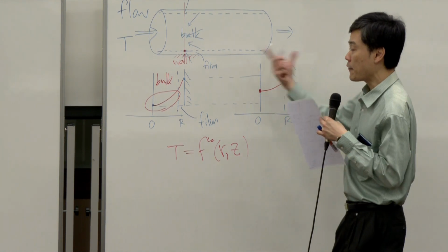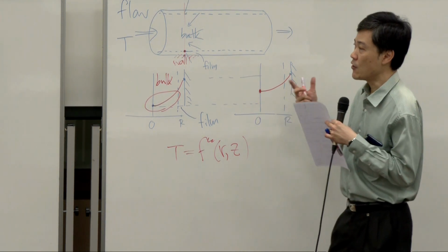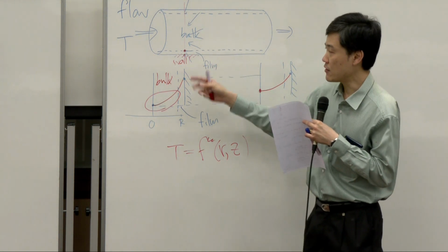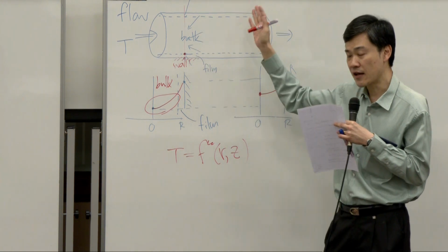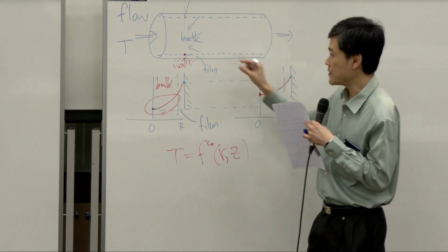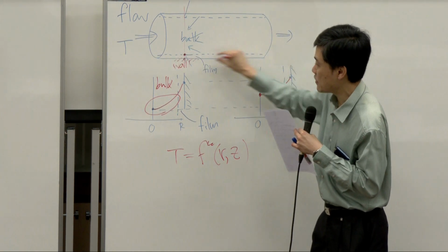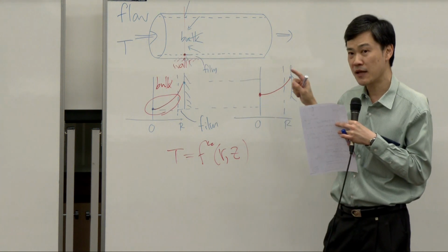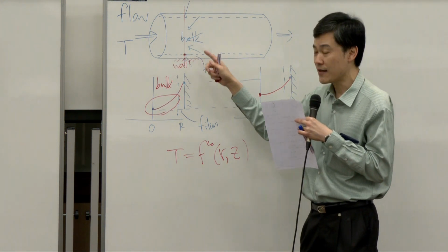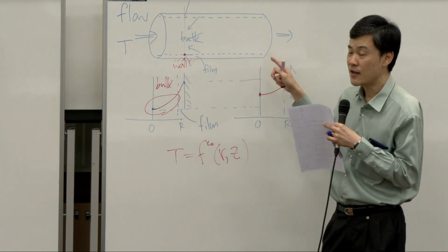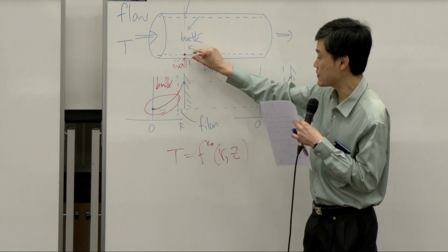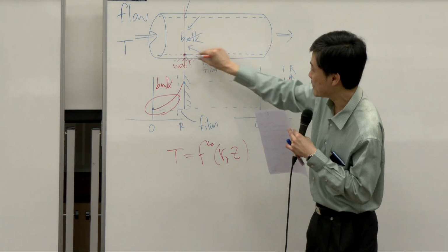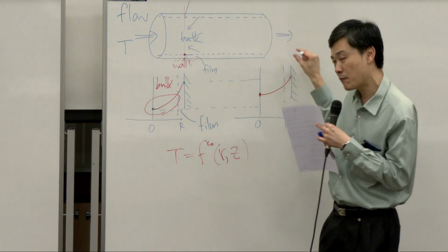Okay? The third complication is that in order to calculate the heat flux or the heat transfer from outside in or inside out, you have to realize if the driving force is changing with respect to the length, that means the amount of heat transfer should be changing. In order to calculate that, you have to know the exact difference of the temperature at every point.